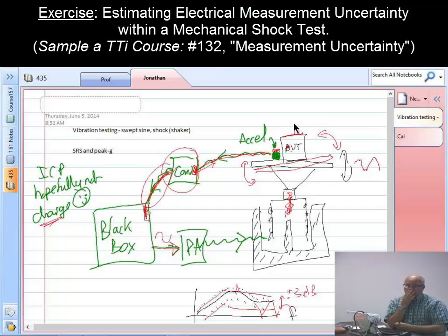Sure. Now whether you do it as 3 separate transfer functions and then work in the frequency domain, or you do time averaging, essentially shorting the 3 cables, like you do with thermocouples. If you've got multiple thermocouples, you can literally wire them together, can't you? You can't actually do that with accelerometers, but in signal conditioning, you're essentially shorting them together and averaging in time, getting the average time signal. So you can do it in the time domain, or you can do it in the frequency domain. As soon as you say transfer function, that means frequency domain.